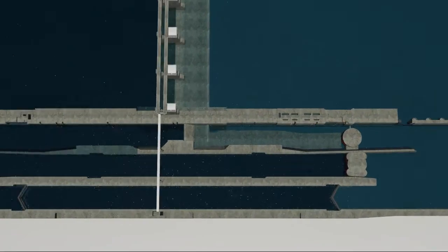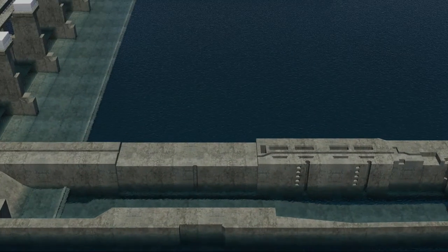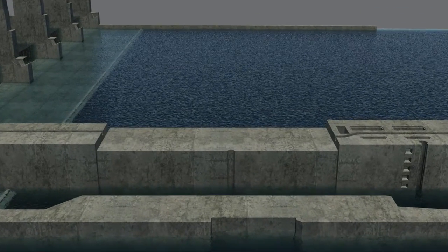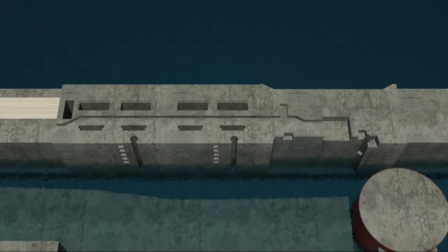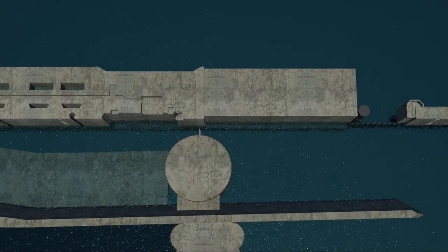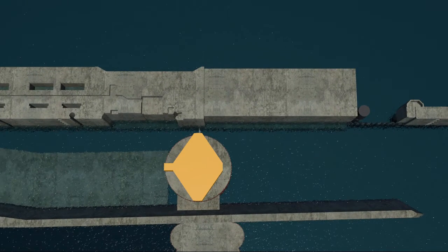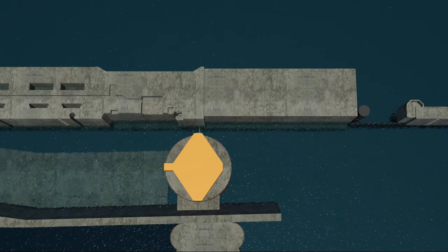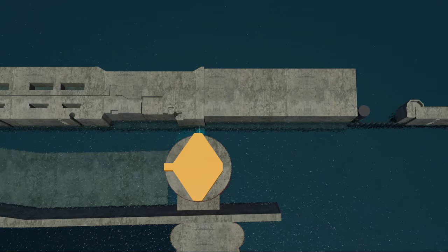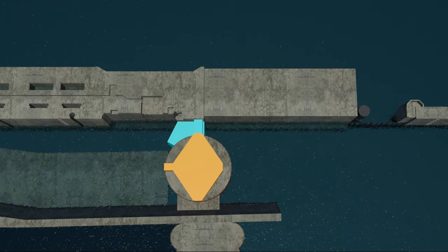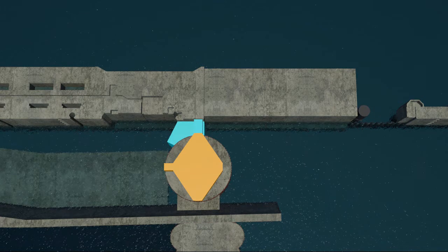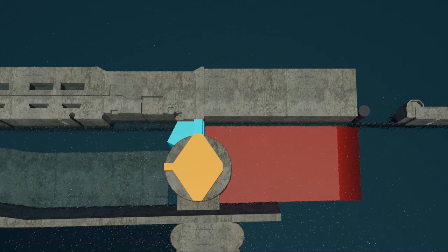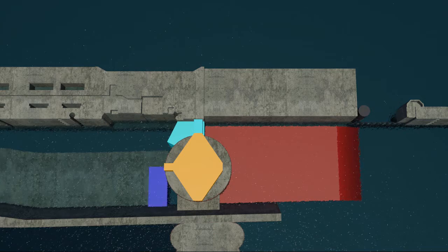In the general construction site model, we first install sandbags atop the new river wall monoliths. Then we install the stability cell concrete cap, remove the original river wall monoliths OR 48 through OR 50, install the concrete wedge, place the stability berm, and then install the coffer wall.